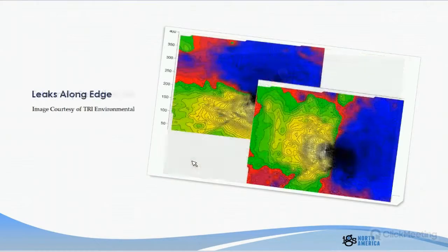And the thing about leaks is that you have to travel across a leak in order to see it, in order to see that sine wave pattern. Otherwise, if you only just walk up to it, you only see half of the sine wave pattern, and it's much harder to see. So at this particular site, let's call it the survey direction map, is shown in the background, which you've already seen. And then the perpendicular map, this is across the front legs and the back legs, dipole is shown here.